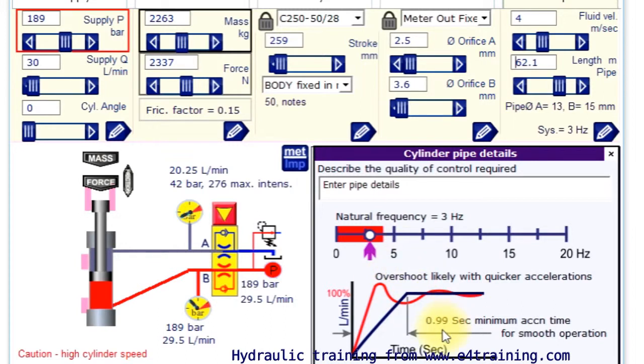We've got a whole second here acceleration time. Typically, you quite often find systems come around about 10 hertz is not unusual. If you're building more dynamic, higher performance machines, you'd be a lot higher. But it's just quite a nice check to see what's happening, see what regions you're in.